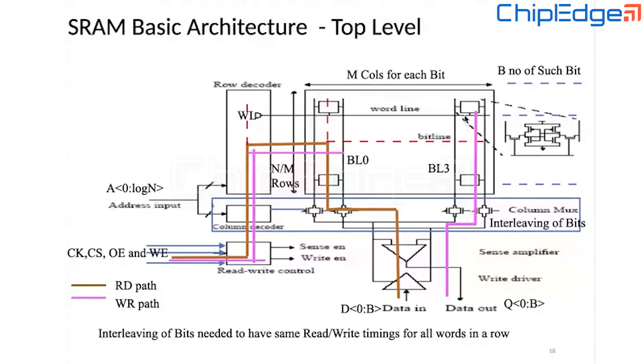So if you see all these bit cells here, on the column side, all these bit cells are sharing one single node which is called the bit line, because this is the bit line which is going to reflect whatever was stored in the bit cell, and this bit line will carry it to the outside world. Similarly, when we have to write, we will be writing on this bit line, and that will get transferred to the bit cell. And which particular bit cell, corresponding to which row, will be selected by this word line, which will come like this. So this is the word line of the bit cell, and this is the bit line of the bit cell. These two are very, very important signals, and they decide eventually what is getting written here inside and on which cell it is being written.